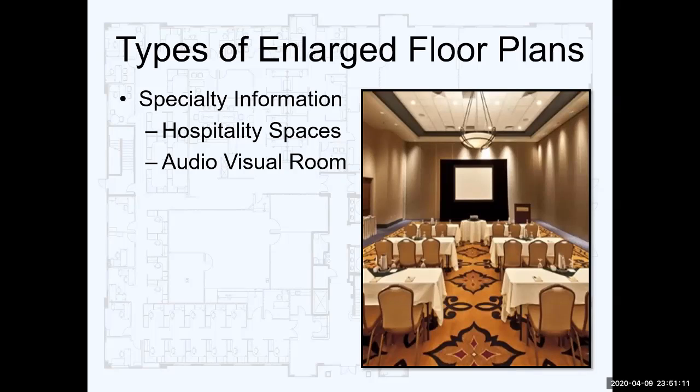Specialty spaces, those who get involved in hospitality will understand the need for drawings to be enlarged for more information. In the slide here, this is just a basic conference room or a breakout room in a hotel, but all these walls here are demountable and they have to be articulated in such a way that they can be stacked back into other areas of the space, and so this can become a large banquet room or a large ballroom.